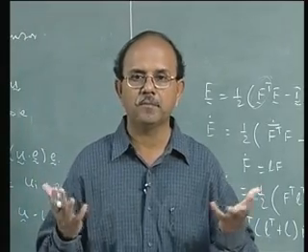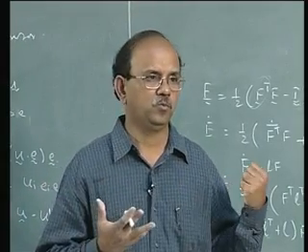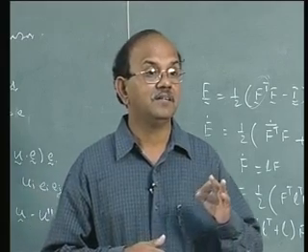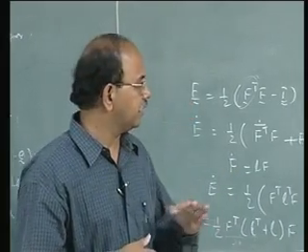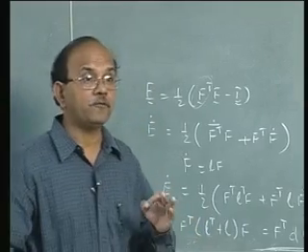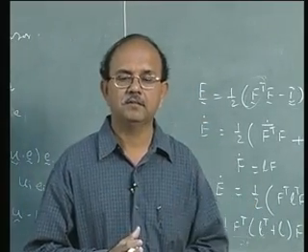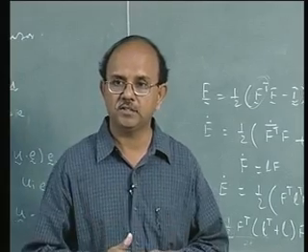Is R dot same as W, which is a spin, which I called a spin tensor? Or in another way, we can say that F had been very neatly decomposed into a rotation tensor and a stretch tensor.